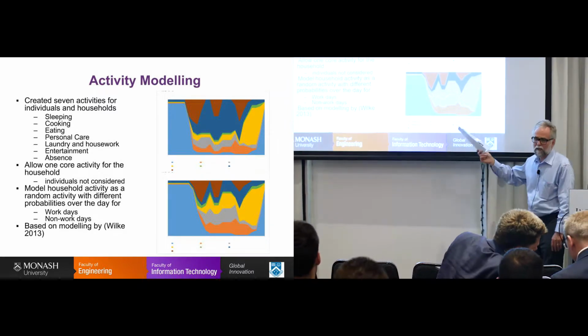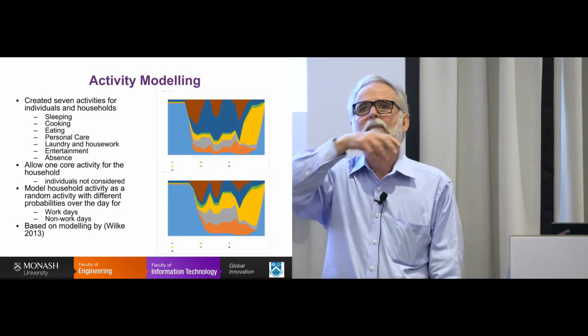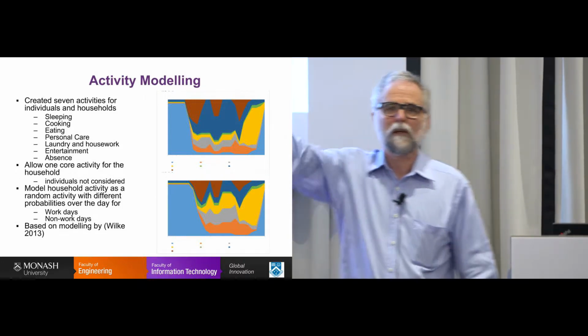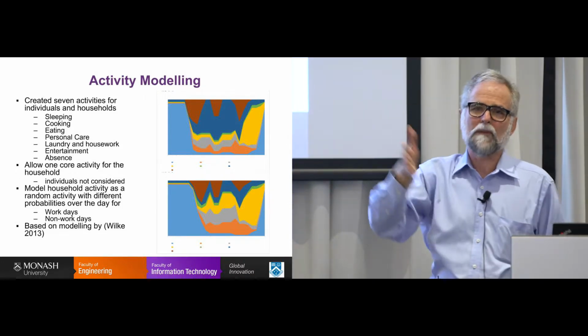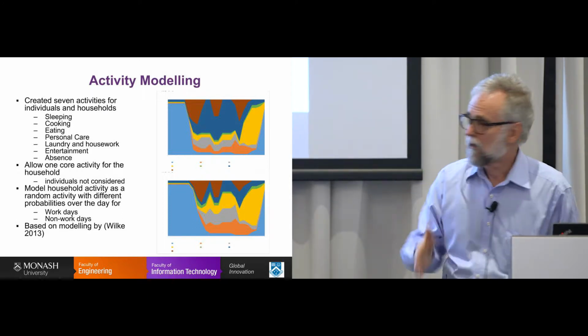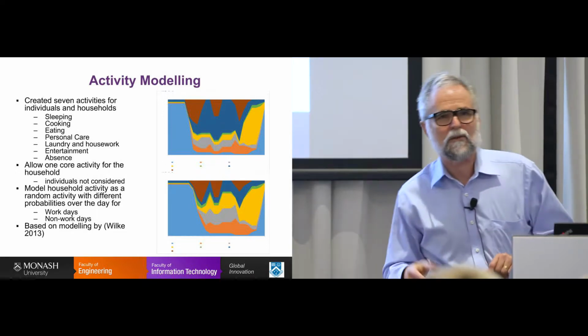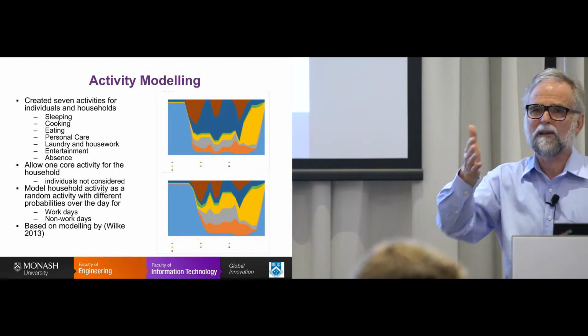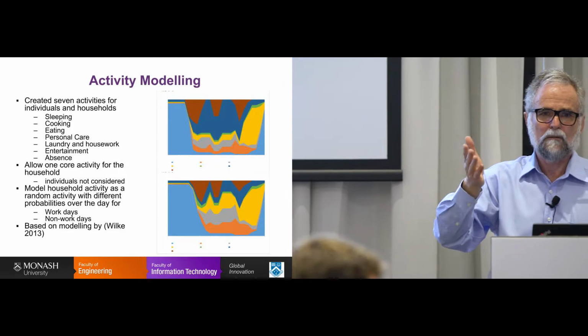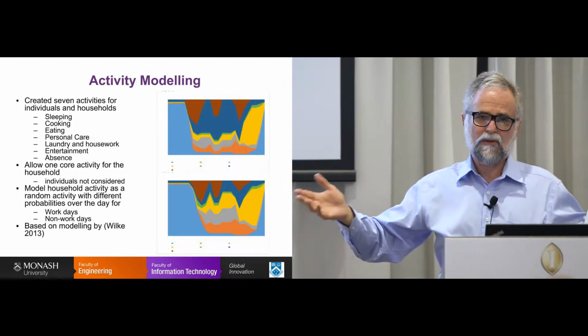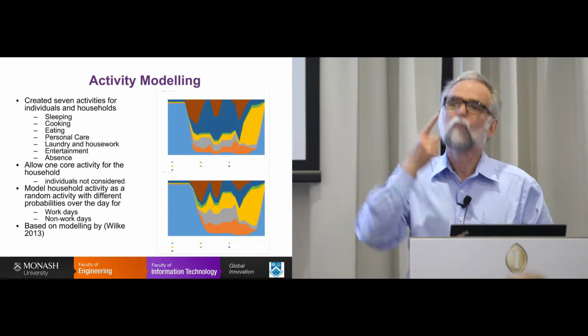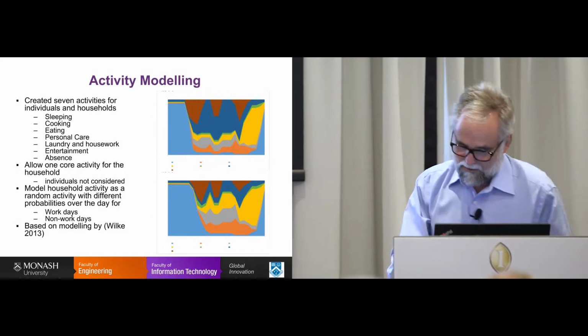I found that the previous method, where you set up a cumulative probability distribution, sample a random number and pick the nearest value, didn't always work with this configuration. So I talked Glenn into changing it so the cumulative distribution is now less than or equal to. And now you can do any arbitrary distribution and sample it in PLEXOS. Win number one.